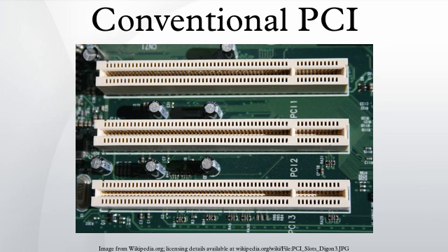This repeats for 3 more cycles, but before the last one, the master deasserts frame, indicating that this is the end. On clock edge 6, the AD bus and frame are undriven and the other control lines are driven high for 1 cycle. On clock edge 7, another initiator can start a different transaction. This is also the turnaround cycle for the other control lines. The equivalent read burst takes 1 more cycle, because the target must wait 1 cycle for the AD bus to turn around before it may assert TRDY.